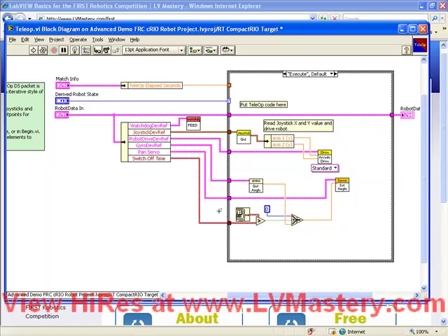I'm going to undo that again and demonstrate one more feature of this idea of pinning down a wire as you go. And that's the use of the spacebar. So again, I'm going to start with a single click, and I'm going to push the spacebar as I'm moving my mouse. So observe that this flips the orientation of that wire branch. And what that allows you to do, especially when you get fast at it, is to route the wire exactly where you want it and not have to worry about an extra pin down.